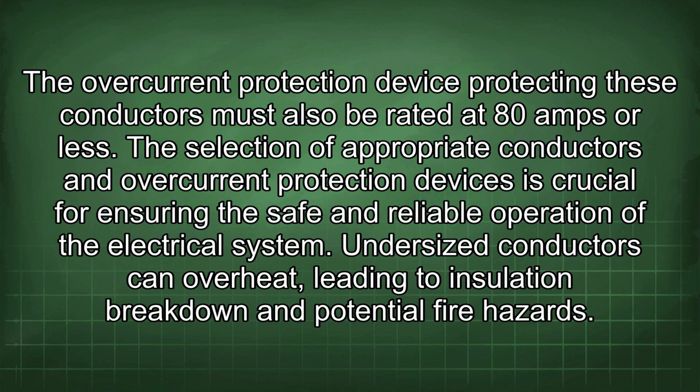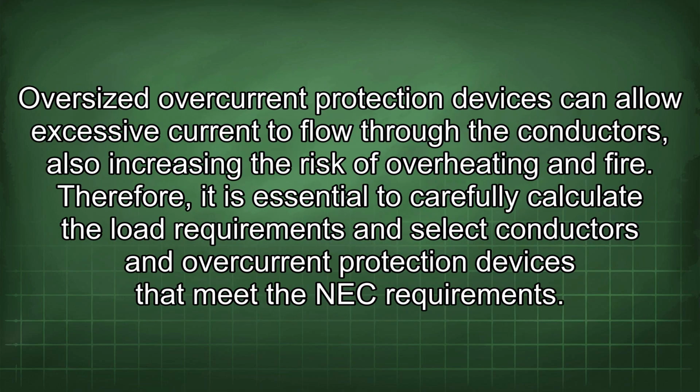The selection of appropriate conductors and overcurrent protection devices is crucial for ensuring the safe and reliable operation of the electrical system. Undersized conductors can overheat, leading to insulation breakdown and potential fire hazards. Oversized overcurrent protection devices can allow excessive current to flow through the conductors, also increasing the risk of overheating and fire. Therefore, it is essential to carefully calculate the load requirements and select conductors and overcurrent protection devices that meet